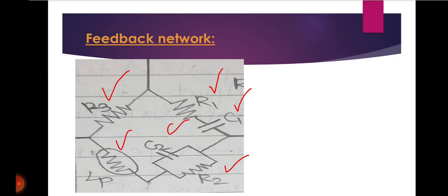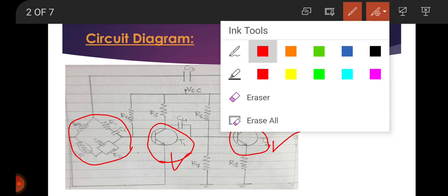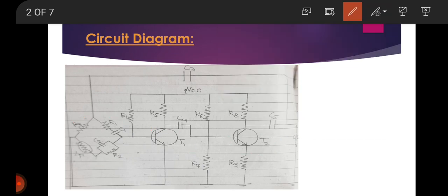This is transistor T1. So this transistor T1 serves as an oscillator and amplifier, while the other transistor T2 serves as an inverter, that is, to produce a phase shift of 180 degrees. So positive feedback through R1, C1, R2, C2 to T1, we get here positive feedback, and the negative feedback through voltage divider to input of T2. This is the voltage divider to T2.